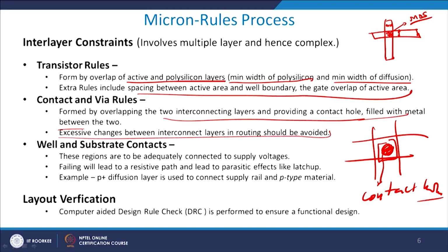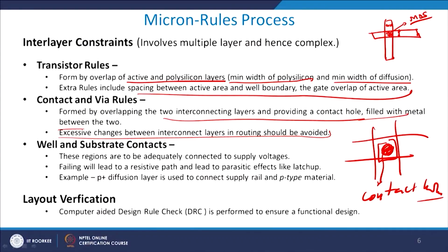I think this is very interesting. I was discussing with you only two metal layers, but you might have multiple metal layers, looking into the fact that you might have multiple interconnect layers. So you have one interconnect layer, 2, 3, 4, the last one becomes your VDD layer, which is the final power supply layer. Typically while designing we should not traverse between layers too much. Within the layer we make a design and then we move to the next layer, and we keep these micron based design rules effectively. Okay with this.